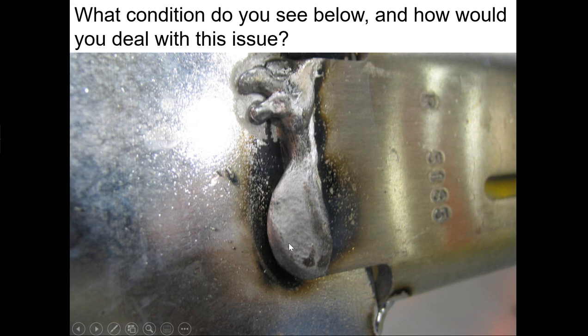And I would go ahead and grind that out because the weld is all okay, basically on the bracket. We haven't even started making penetration there. Now, as I'm grinding this out, first observation: any cracks in base metal? No cracks in base metal outside of the weld zone, re-weld it. If I grind it down and look underneath and see any cracks outside, scrap it. Don't think about it twice.